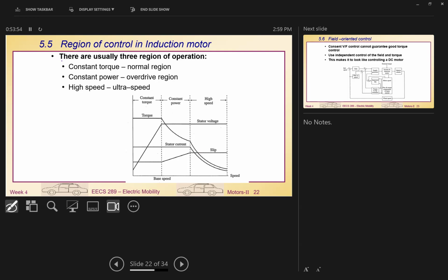But now go to here, the end of the base frequency. The motor voltage is up to the maximum voltage of the motor, say 200 volts. You can't increase it more than 200, otherwise you push your motor winding to too high a voltage. So you must stop the voltage there. Even though you intend to use constant V/f control, you cannot increase the voltage.